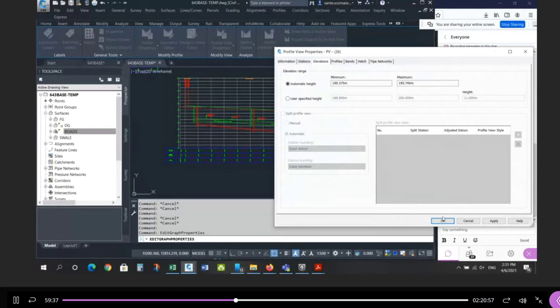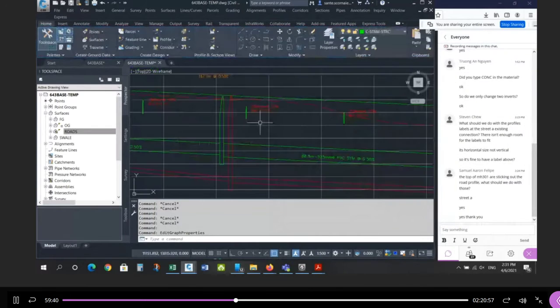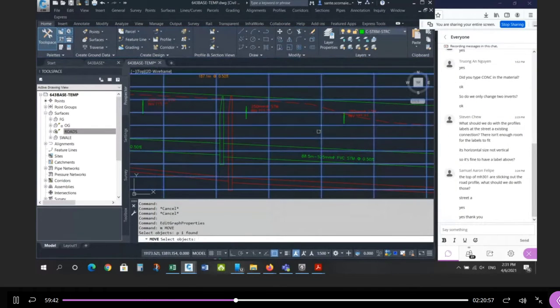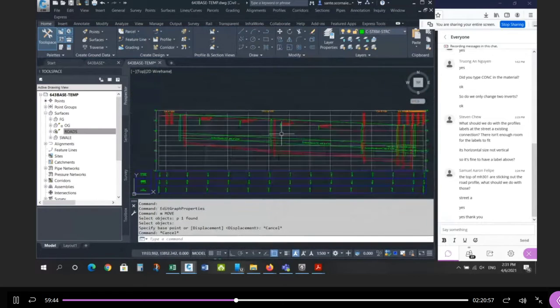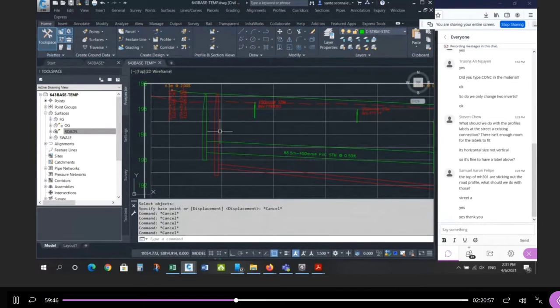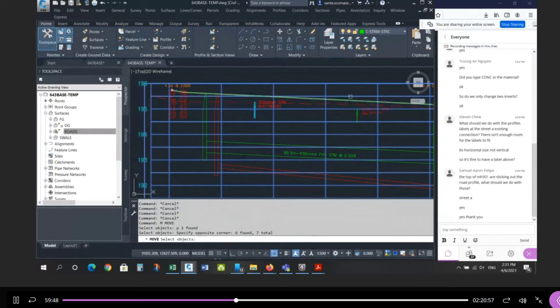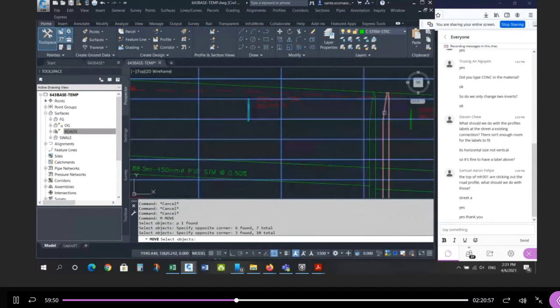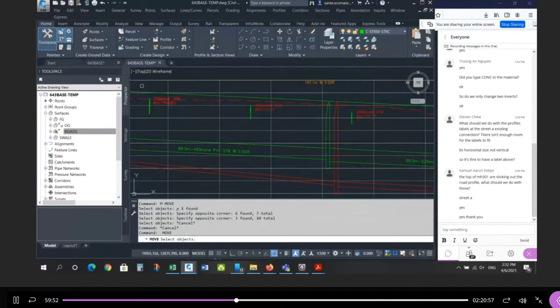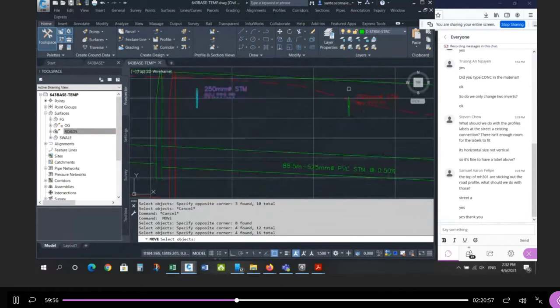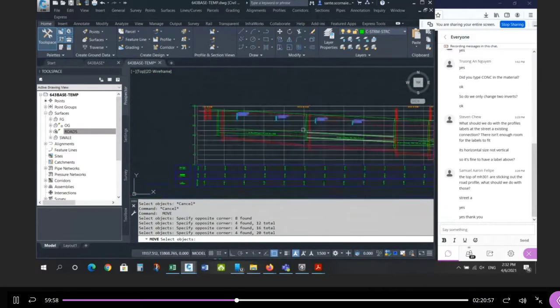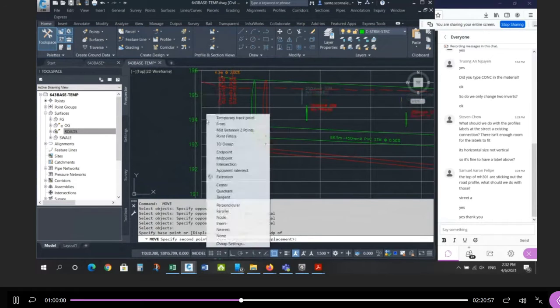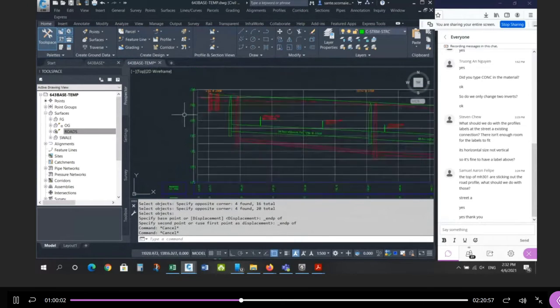So if we go back to this is automatic and say, okay, now it looks funny, so then you got to move those things back to where they belong. And it's typically a vertical shift of a meter or two, whatever your change is with the bottom number. Okay, does everybody see that behavior? It's important because it's going to come up again when we do the water main, which I'm about to show you. All right, so these have to go down by a meter, so from 5 to 4, and now they're back where they're supposed to be.